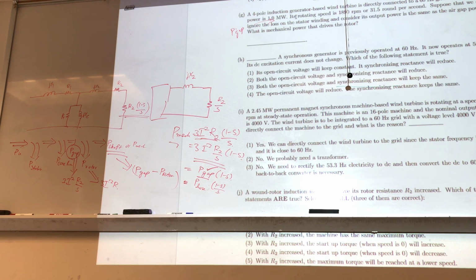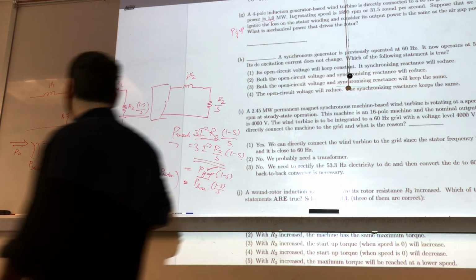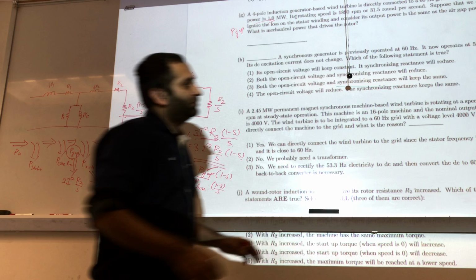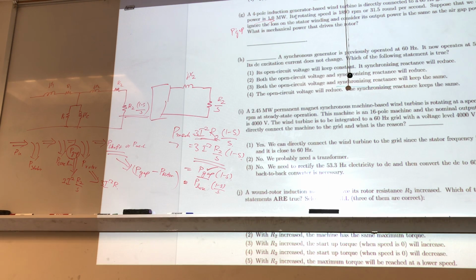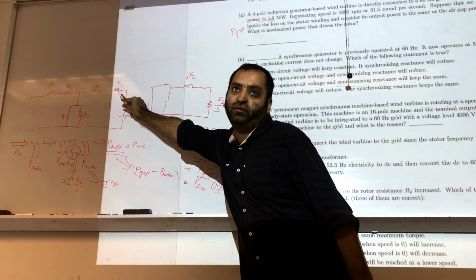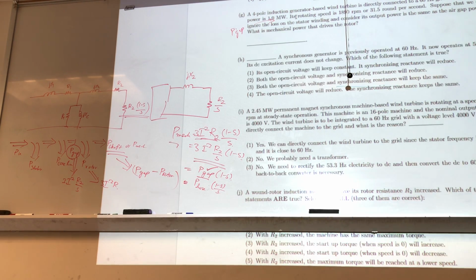So suppose if I go back here, you have the stator power here, then because of the core there will be loss, which you call core loss. Then after removing the core loss, that's the power we transfer from the stator to the rotor. And once we are in the rotor, we'll have the loss due to the resistance R2.